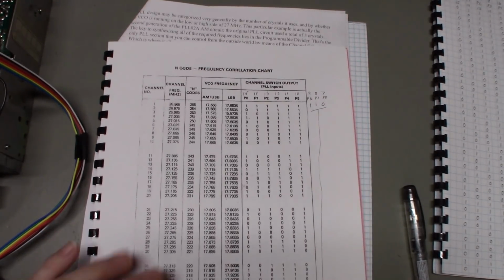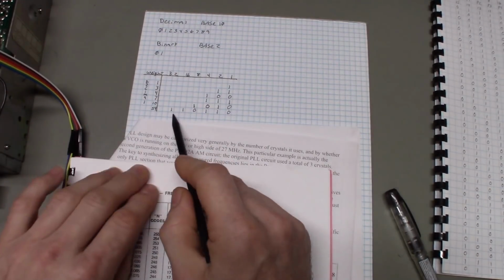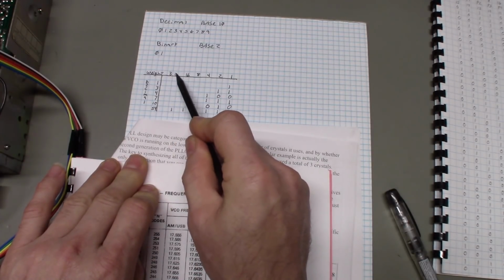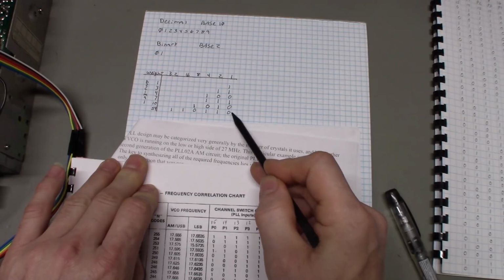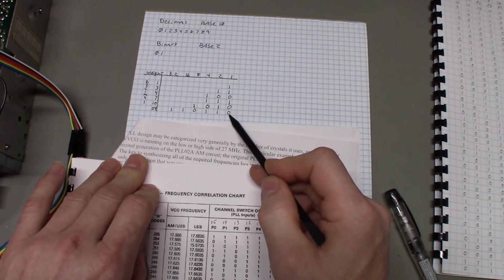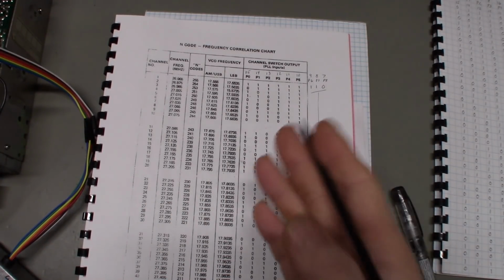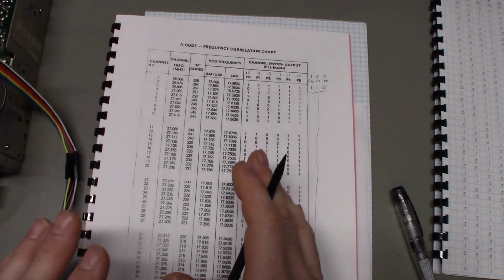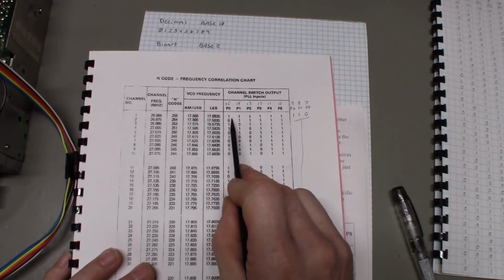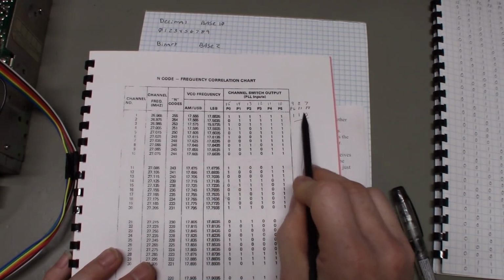What I mean by that is, remember, I said when you write binary code, it's supposed to be most significant digit first, meaning the digit with the most weight, and the least significant digit, that's always going to be the 1, should be the last digit. This ain't like that. Don't blame me, blame the engineers or whoever decided to number these things or put it in these books. It's backwards. This is the least significant digit. Over here is the most significant digit.